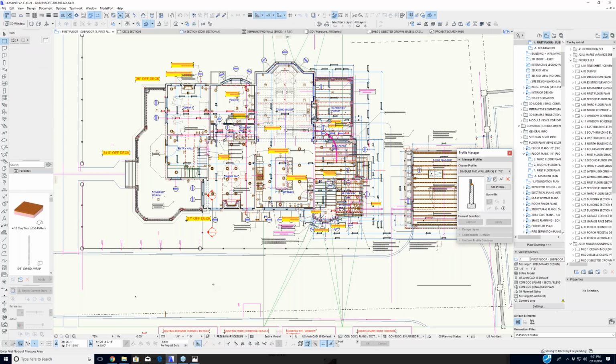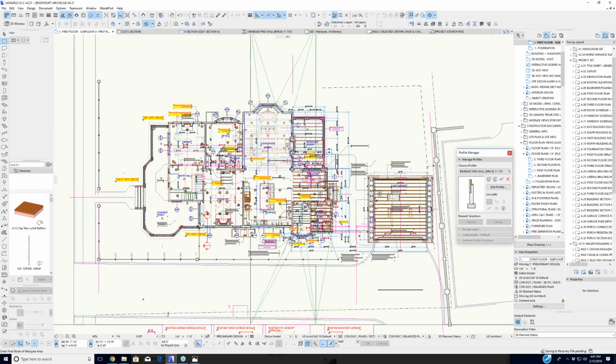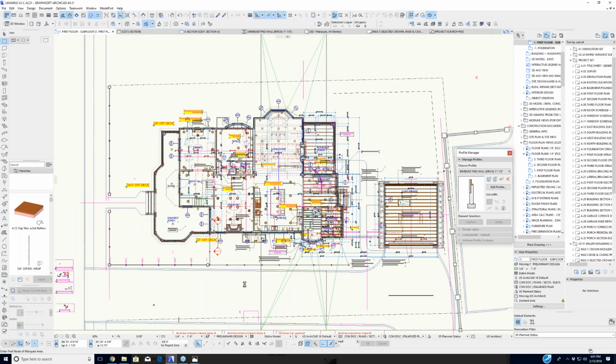It's another thing as far as a conversation on hardware. I'm using a PC. I try to upgrade every 3 years. I don't recommend trying to get a machine to last 4 years unless it's being used for other things than ArchiCAD. But ArchiCAD is a very robust program. You need a lot more RAM than they recommend. On the Graphisoft website, they're going to give you what works, but you really need a lot more than that. And I would highly recommend solid state drives. No more of the spinning disks and that kind of stuff.